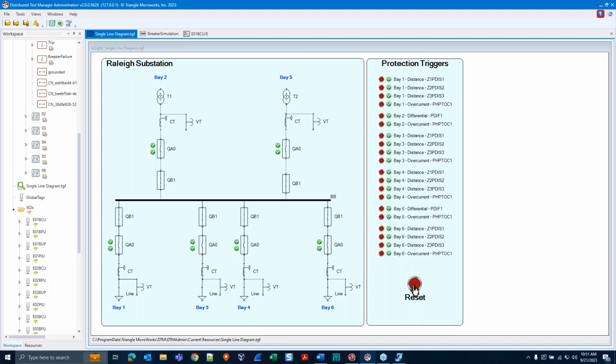You might recall during our last webinar, when I was configuring all of this using Helix, configuring my whole SCD, I also put in some breaker failure functionality. So you might be wondering what these 2 green check marks do next to each breaker. Effectively, the first one disables the trip coil that you might have as part of an actual breaker out in the field. And the second one disables the retrip coil, which would typically be energized as a secondary effort to retrip if the first one should fail, and might be used by a breaker failure function, for example.